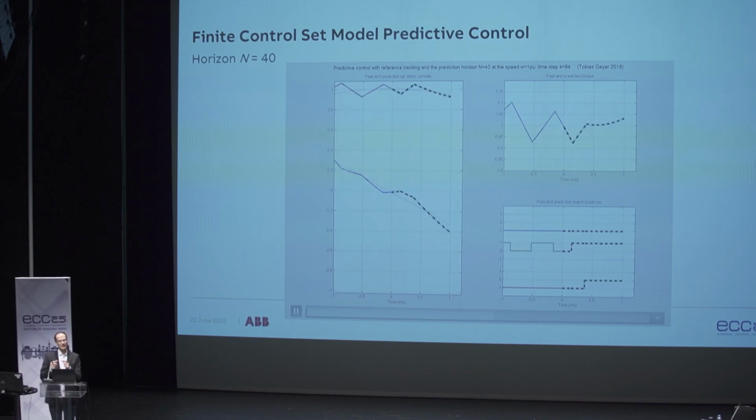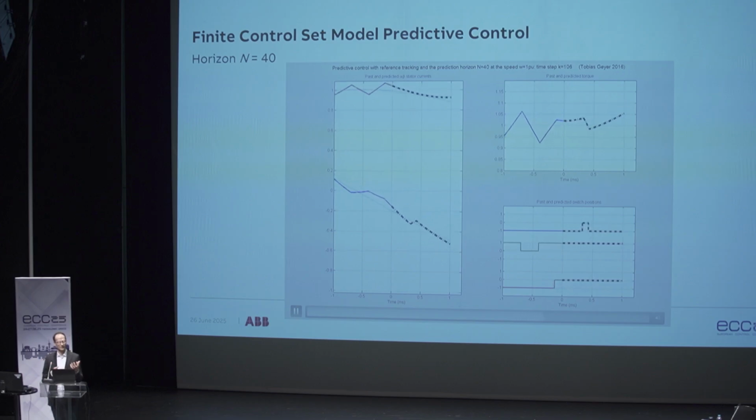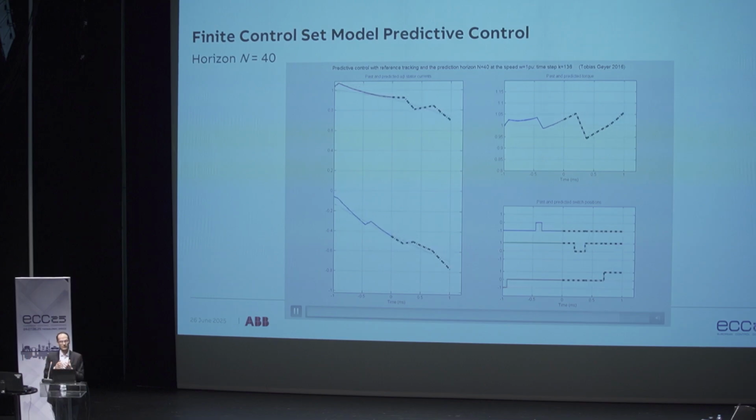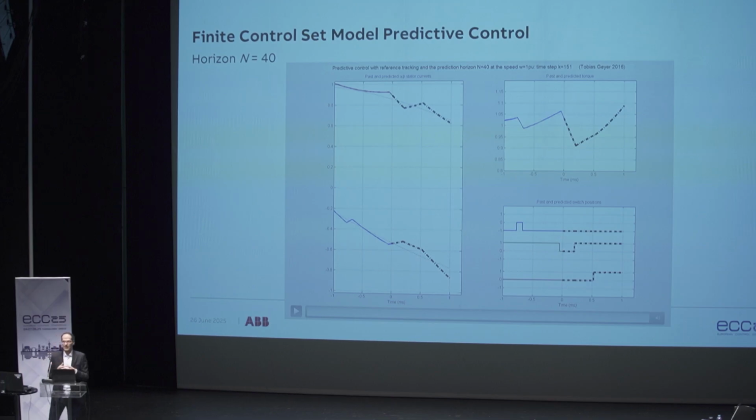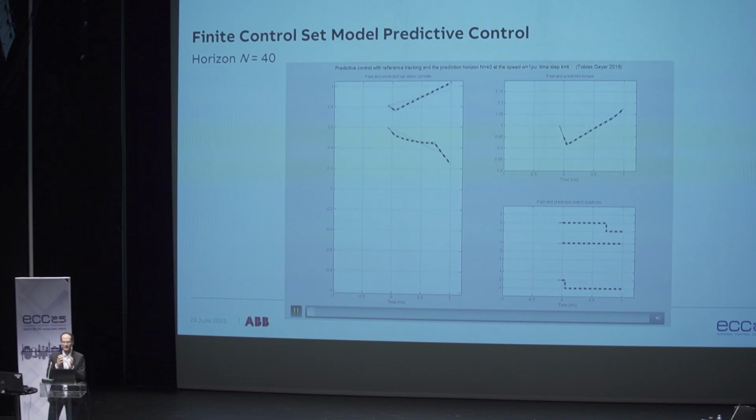Now, when you think about the complexity of solving that numerically, you have 3 to the power of 120 integer combinations, or 27 to the power of 40. And that's equal to 10 to the power of 53, and that's effectively the atoms in the sun. So you have an extremely hopeless problem to solve, but you can solve it because this lattice is almost orthogonal, and because the sphere decoder works really well for it.